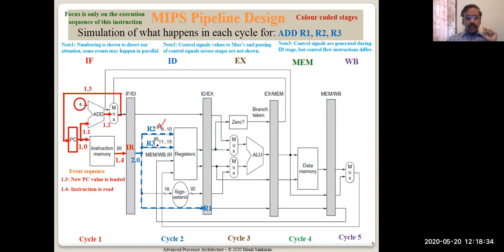You understand these two. What about this? If you recall, I told you the result is written into R1 and the writing of the result is happening in the write back stage, right? It's not happening before. So during this stage, it doesn't know which register it is supposed to write into.